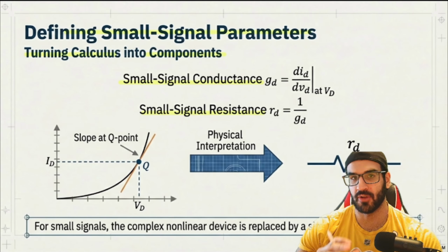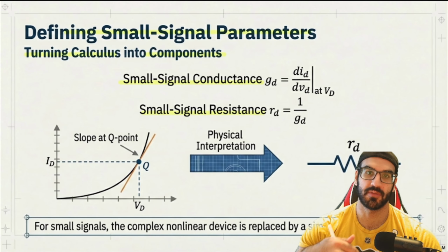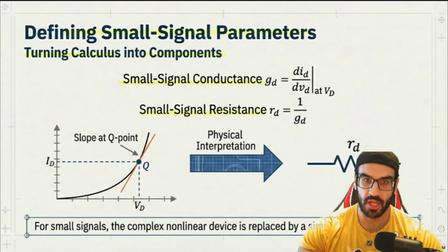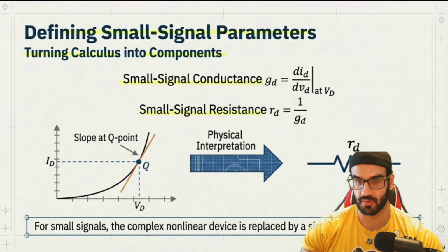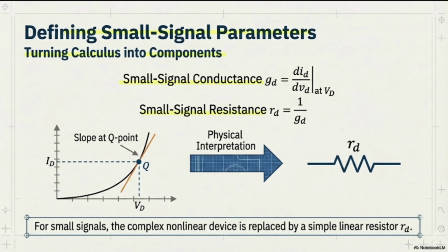So right now I can consider a conductance. As you guys know, the conductance is the reciprocal of resistance. By using that, I can convert my nonlinear component to a linear component. The linear component is obviously a resistance. We can use that. So the GD, based on the conductance, is going to be the derivative dI_D over dV_D at V_D itself.